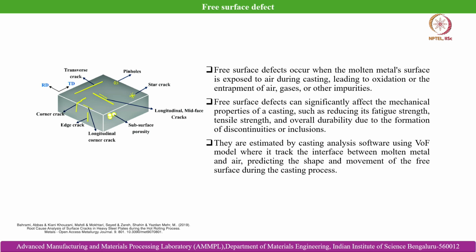Free surface defects can significantly affect the mechanical properties of a cast part, such as reducing its fatigue strength, tensile strength and overall durability due to the formation of discontinuities or inclusions. And then they are estimated by casting analysis software using the volume of fluid model, where it tracks the interface between molten metal and air, predicting the shape and movement of the free surface during the casting process.